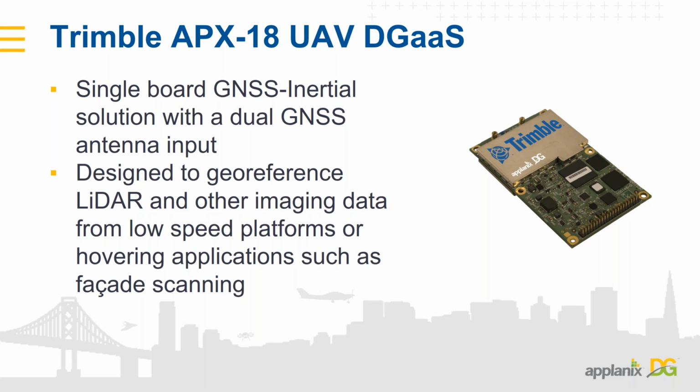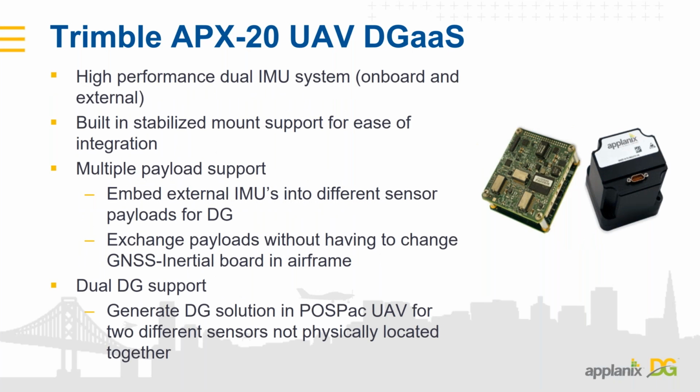Because basically what happens is that when you're stationary, you're not really leveraging the value of your INS solution. So we offset that with the second antenna configuration, and that allows us to get accurate results from your infrastructure. If you didn't have that, you'd probably see some skewing at the edges of, say, a bridge or whatever. But with this configuration, we get a very, very accurate representation of that scanning target.